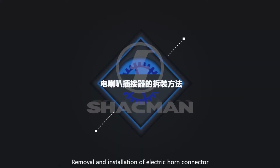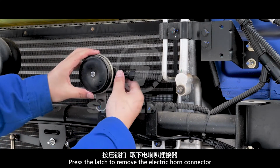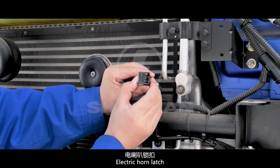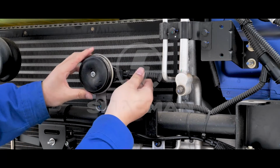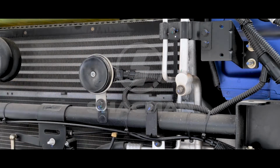Removal and installation of electric horn connector. Electric horn connector. Press the latch to remove the electric horn connector. Electric horn latch. Pull back the electric horn connector. Make sure the connector is connected reliably.